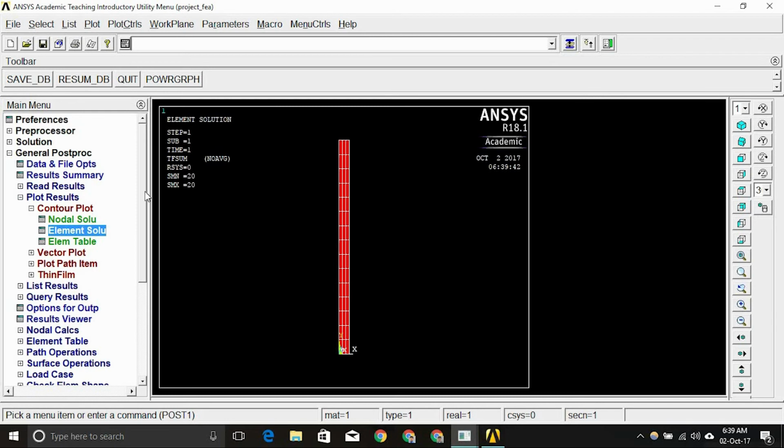In the 3D case, we calculated with 8 nodes, which was reduced to 4 nodes in the 2D case. The second thing is, the machine created a lesser number of elements, thus a lesser number of nodes in totality. So the calculation time as well as the resources that we used for the process reduced considerably in this case.